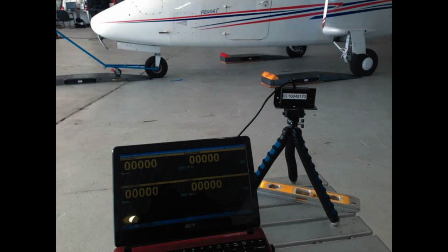Then, its weight and moment are subtracted from the weight and moment of the aircraft as weighed. The amount and arm of the undrainable oil are found in Note 1 of the TCDS, and this must be added to the empty weight.